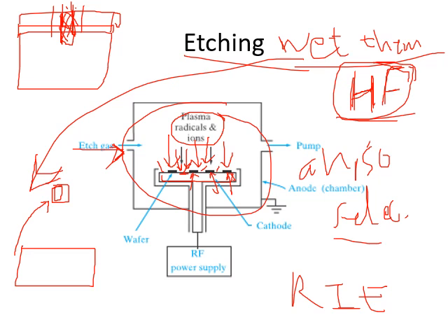Are you following? So what we are doing, basically, we are bombarding. You can understand this word better. Bombarding the plasma radicals and ions with very high kinetic energy. Because of that bombarding, the things will get etched away, right? The unwanted materials will get etched away.